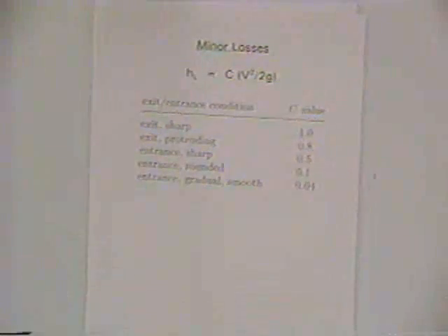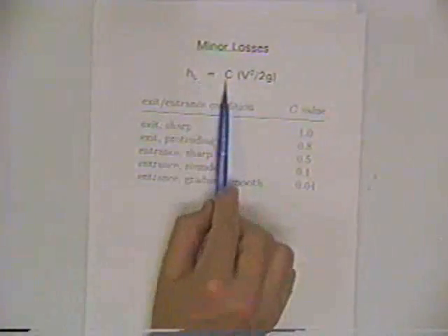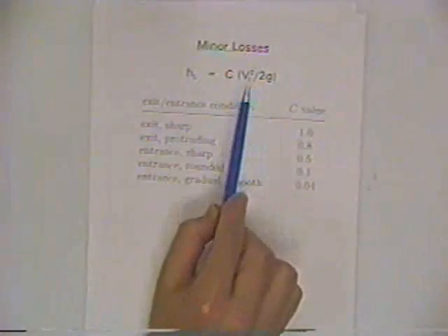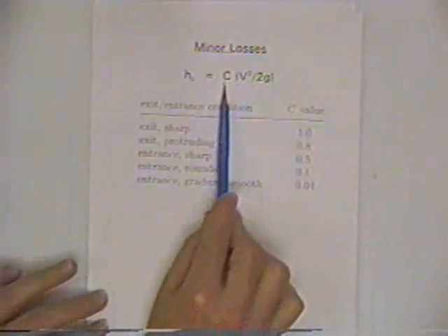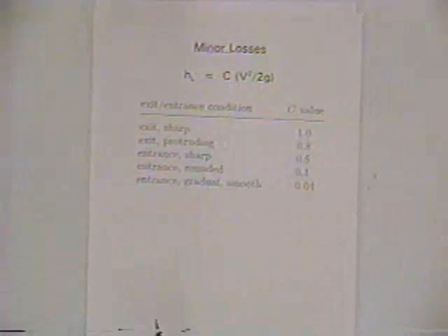And so a common term for these other head losses is minor losses. In many applications, the minor losses might be quite major, but that's what we call them. They can be expressed in different formats. In your reference manual, the formats are always in the general form of head loss being some minor loss coefficient times a velocity head. And your reference manual uses the term C for the minor loss coefficient.